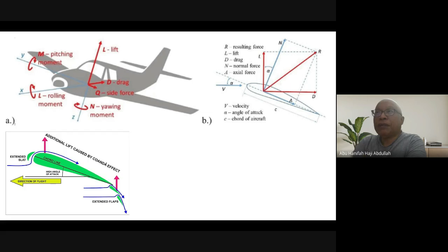What happens is, you can see on the right diagram, there's an airfoil with flow over it. As flow goes over a surface, there will be a force perpendicular to that surface. That is fluid mechanics, fluid dynamics. The science is that as anything flows over a surface, a force is generated 90 degrees to the surface.